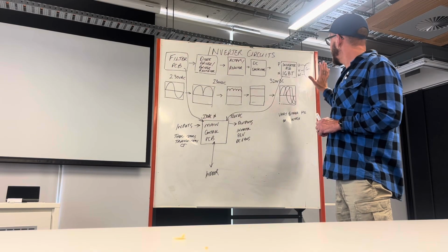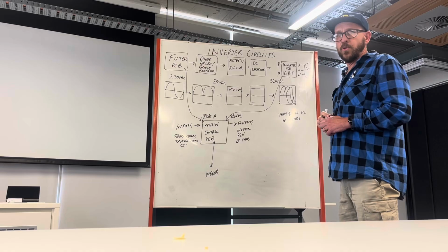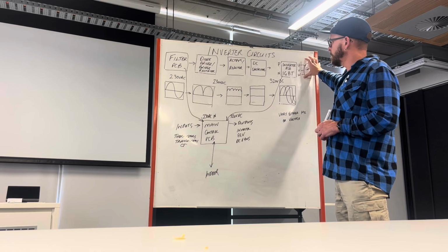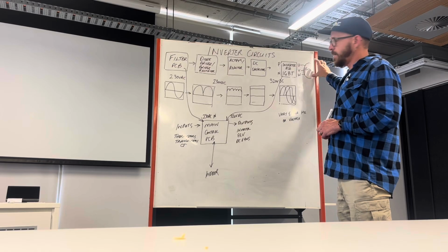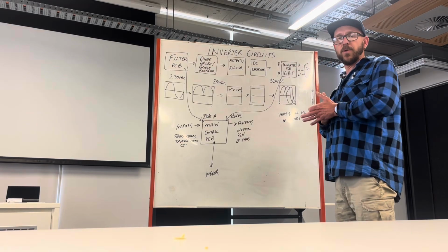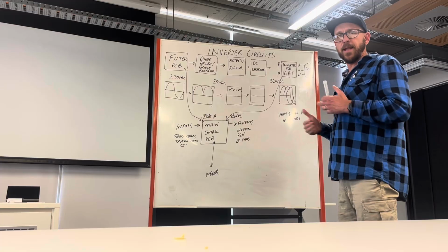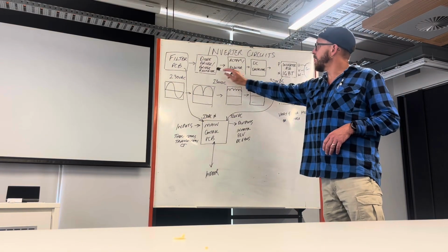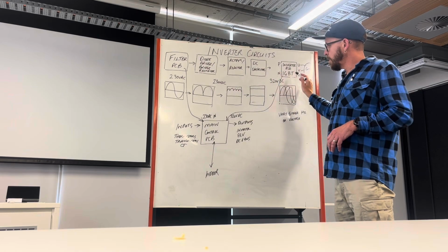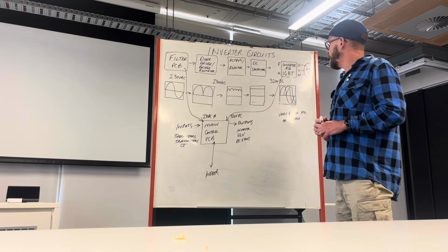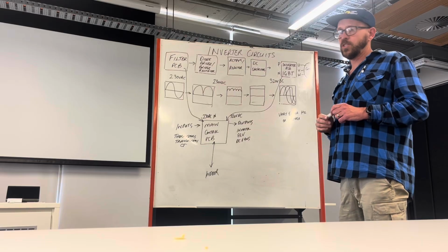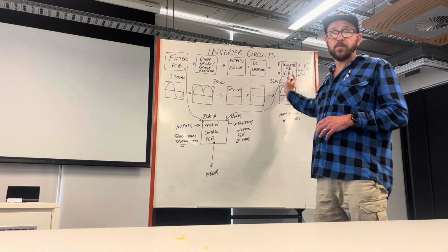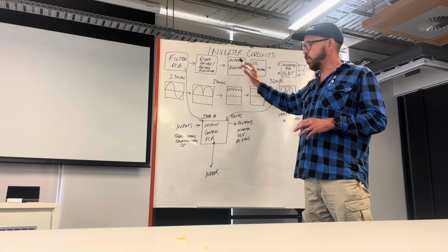So we've spoken about the compressor. It is possible to put an inverter checker on here in place of the compressor. So we unplug the compressor and put in an inverter checker, see if we're getting an output from the board. But typically there are ways of checking a lot of these components, making sure they're all okay. If you've got your head around what sort of voltages you're expecting, you can go through and look for those. As I said, some of this model will be in one board.